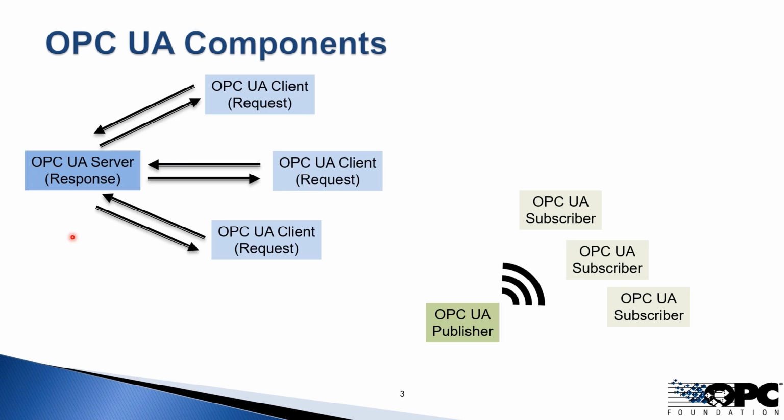As an example, let's assume that my OPC UA system consists of just this one OPC UA server, and I want to provide user access control to multiple clients that may be interacting with me. In a system like this, it's reasonable that the OPC UA server would store and maintain the usernames and passwords for all of the potential users of my server, and each time the check for the user and password would be done by the server.